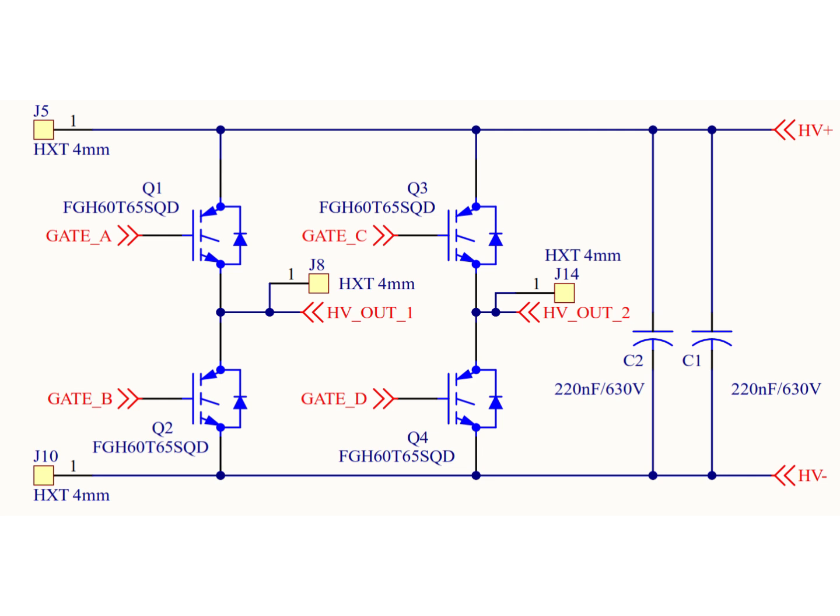The device used here is the FGH60T65 SQD, a 650-volt field-stop trench IGBT. The 650-volt collector-emitter rating is chosen deliberately. With a 400-volt DC bus, hard-switched inverter designs typically require a safety margin of 1.5 to 2 times the bus voltage to safely handle switching transients, parasitic inductance spikes, and any regenerative energy from the load.